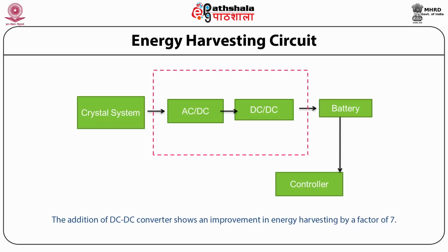It consists of a switching device in parallel with the piezoelectric element. The device is composed of a switch and an inductor connected in series. The switch is in open state except when the maximum displacement occurs in the transducer. At that instant, the switch is closed and the capacitance of the piezoelectric element and inductor together constitute an oscillator. The switch is kept closed until the voltage on the piezoelectric element has been reversed.